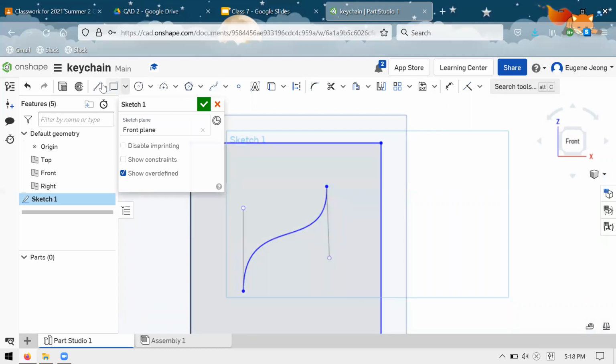In order to fully constrain a spline, you need to fully define 4 points, the endpoints and the two guide position points. So you'll see that I can specify dimensions like this. For a point, all you need to specify is its position and it will be fully constrained. So at most, you'll need 8 different dimensions in order to fully dimension a spline.